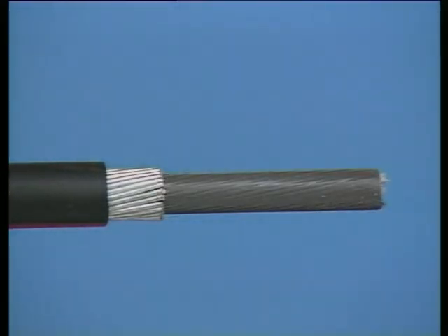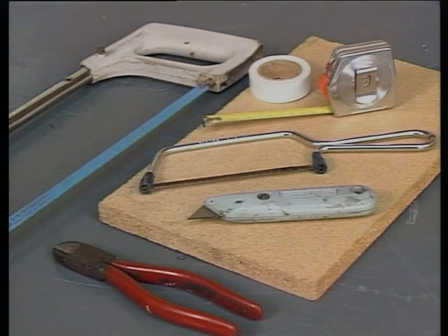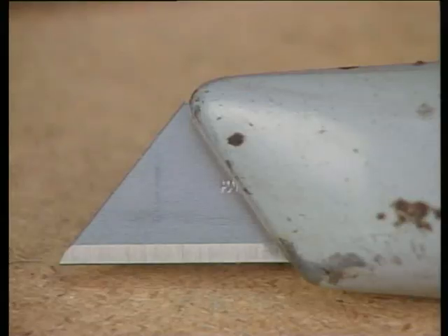The objective of preparing a cable end is to remove the layers of sheath, armoring, bedding, and insulation in a prescribed way and to specific dimensions. To achieve this result, you will most often need to use both measuring and cutting tools, along with some simple marking out aids. At this stage, it should be mentioned that cutting tools must be sharp, as dull tools end